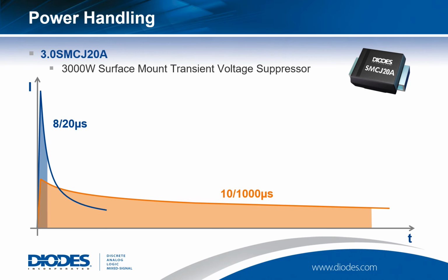There are two standards for this that are widely used, the shorter 8/20 microsecond pulse and the 10/1000 microsecond pulse. It's important to note that the times given here are elapsed time from zero, so the 8/20 pulse spends 8 microseconds climbing up to its peak, and then a further 12 microseconds declining to 50% of its peak value. The 10/1000 pulse similarly spends 10 microseconds going up and 990 microseconds coming down, although the difference between 990 and 1000 in that case is obviously trivial.